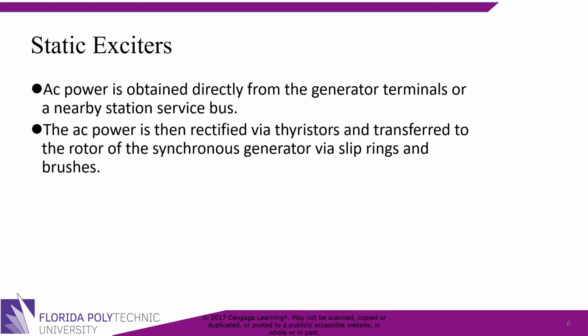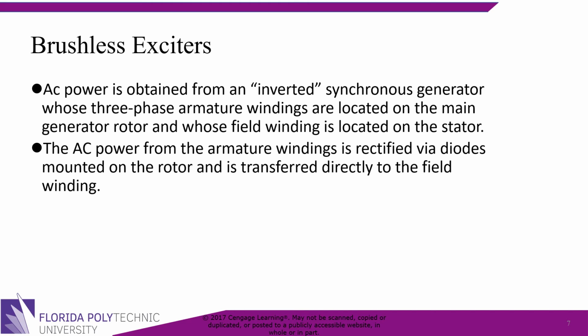Static exciters. AC power is obtained directly from the generator terminals or a nearby station service bus. The AC power is then rectified via thyristors and transferred to the rotor of the synchronous generator via slip rings and brushes.